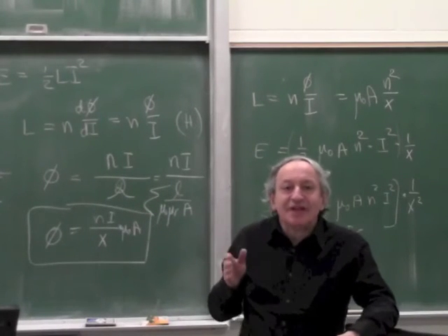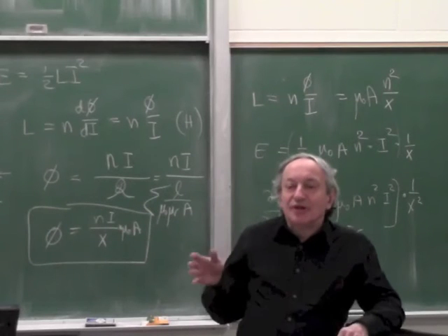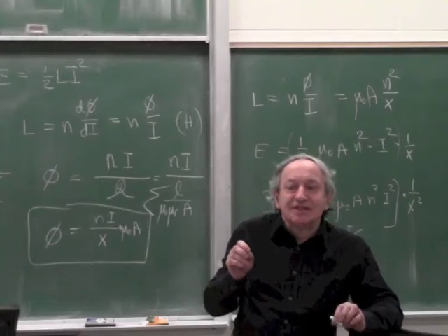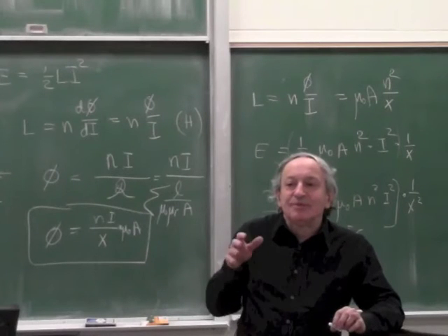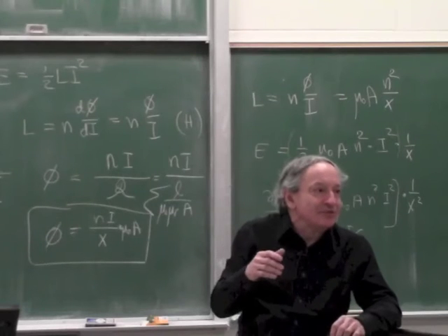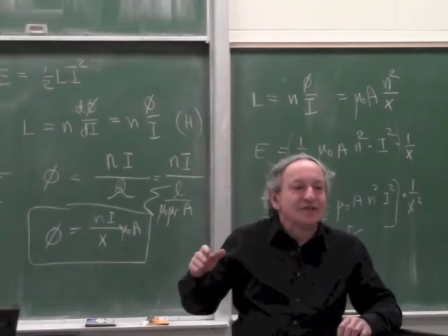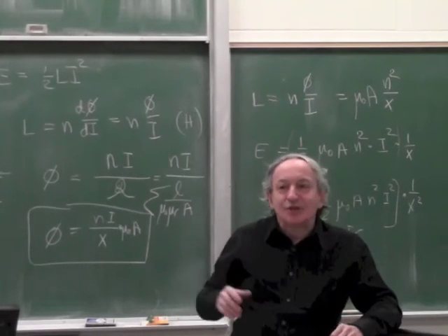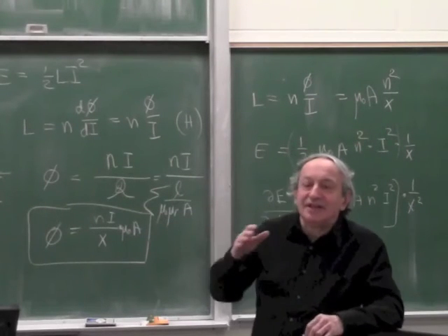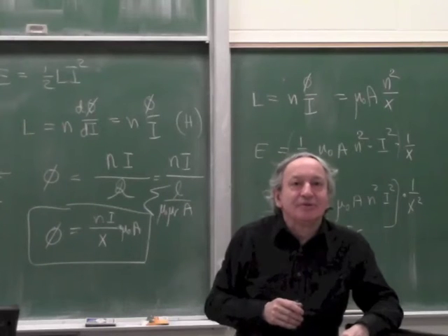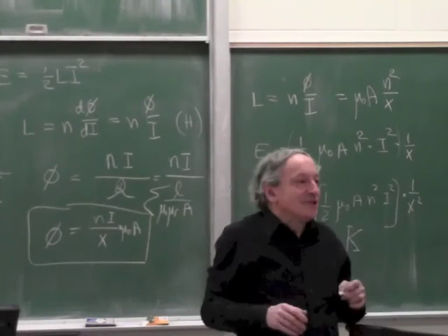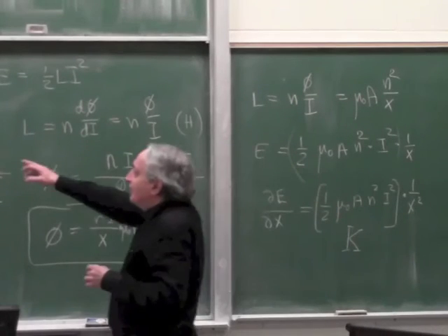So when you have a fixed gain servo system, like a moving coil actuator, you fine-tune the system so that you just reach stability, but you maximize the gain you could. So you look at the peaking, you look at the phase shift, you say, okay, I can add a bit of gain because I still don't have a 180 degree phase shift, so you maximize the operation. But here you have to do this fine-tuning for the highest gain, and at any other position of the actuator there will be lower gain, and the system will work poorly. Is that clear? Good. So that's the problem with systems with variable gain in servo.